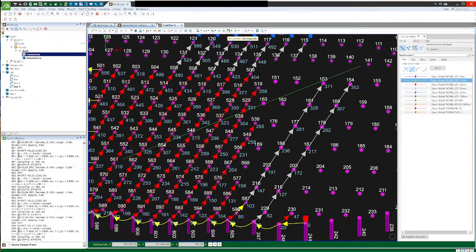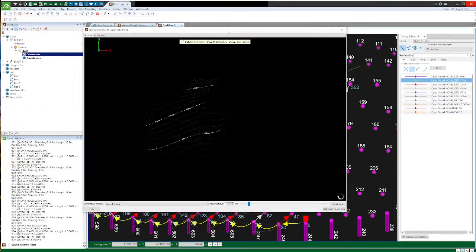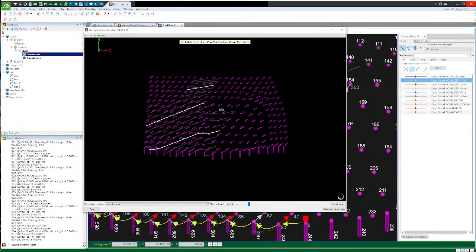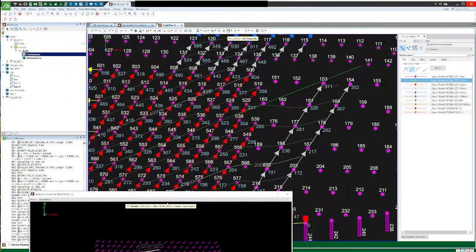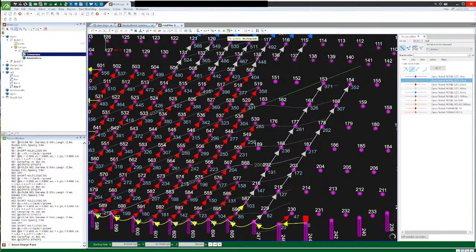And in order to see those contours show up, we're going to put on the blast modeling again and hit a timing contour there. I'll come up again and bring that up into the screen. And you can see here it's not quite right. We've got a kink, so our times are not right. And that's how you read a contour, is your contour should be forming what we just talked about. So I think maybe I didn't use enough 42s in there.